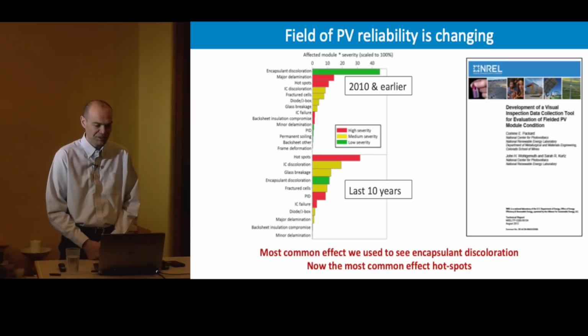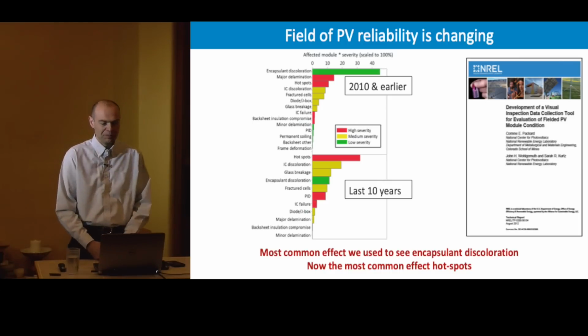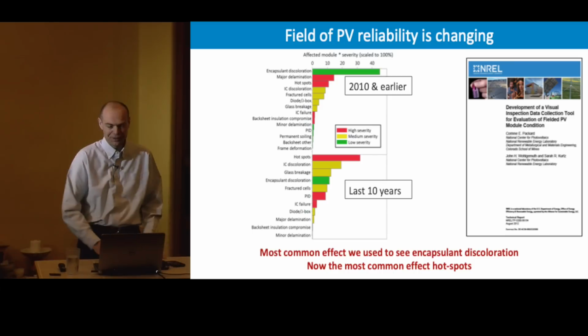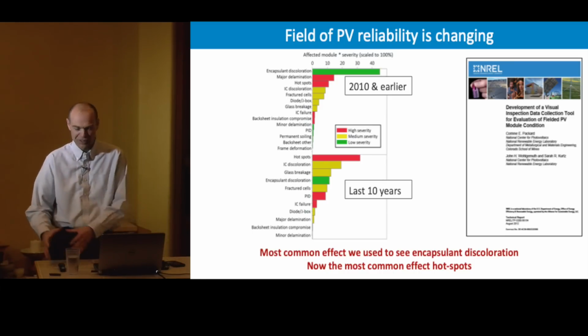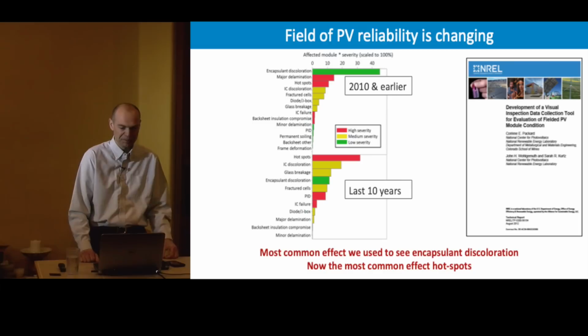But some of the impact is that you have some cracks that can form, but you only see it by EL measurements. They can grow later, but they don't have to. So this is a little bit of still research. There's some in the PV community that think cracks are really bad, and there's some people in the PV community that think cracks are fairly benign. The truth is probably that it depends on how the crack goes across the fingers and the bus bars, so it can have various impact. But yeah, hail can have an impact too.